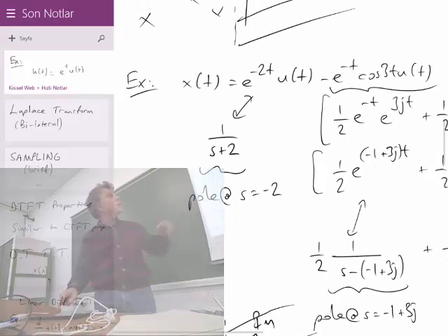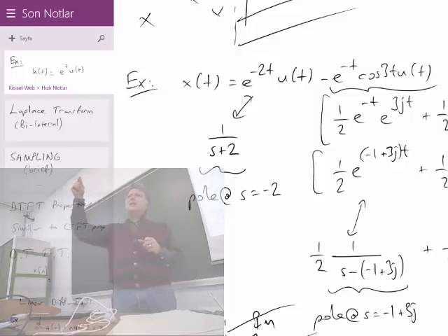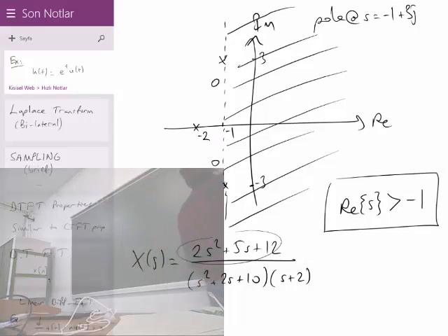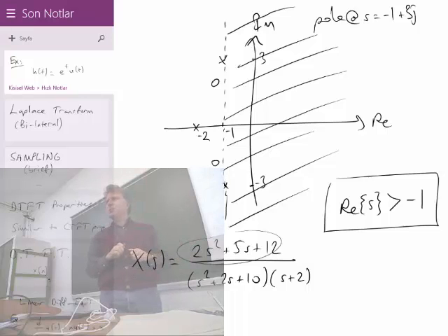And this oscillatory component, the cosine component over there, is an oscillation, which in the exponent means there is e to the j something, because that is a sinusoid. You remember that? e to the j omega t is a sinusoid. So if you have a cosine or a sine like that, then the poles do not appear on the real axis. They also have some imaginary components to form e to the j omega things. That is the reason of oscillation. So oscillations are caused by inserting poles and zeros, not necessarily along the real axis, but somewhere else in conjugate pairs. If you insert some poles, then it means you are having some oscillations. You have some cosine terms. Otherwise, you have some real exponentials only. If all the poles are on the real axis, then you have no oscillation.